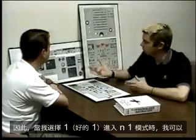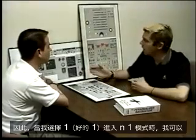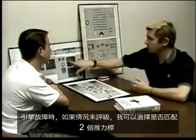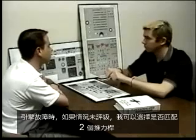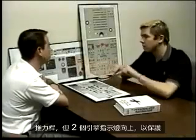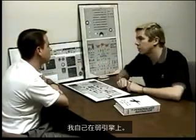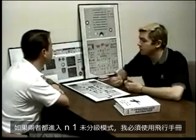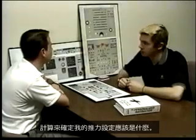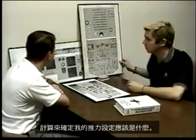So when I select the good one into N1 mode, I can then, if I have an unrated situation on the bad engine, match the two thrust levers up, or not the thrust levers, but the two engine indications up, to protect myself on the weak engine. If both were to fall into N1 unrated mode, I'd have to use flight manual computations to determine what my thrust settings would have to be.